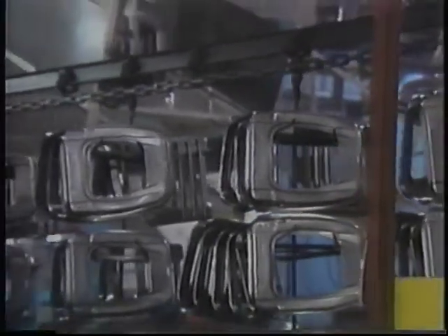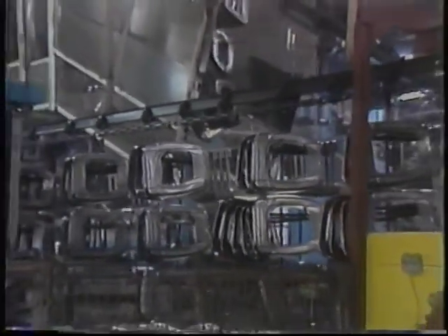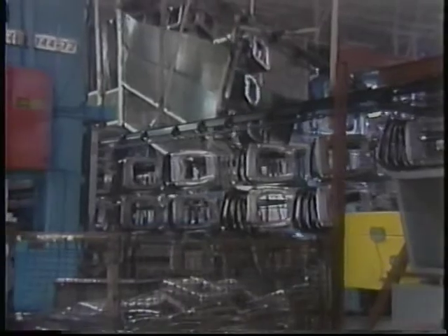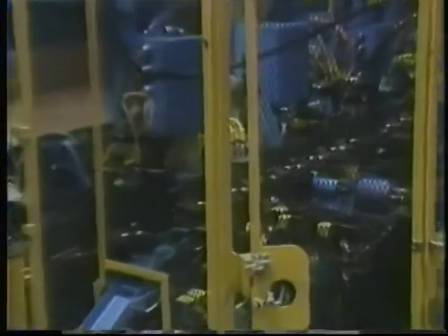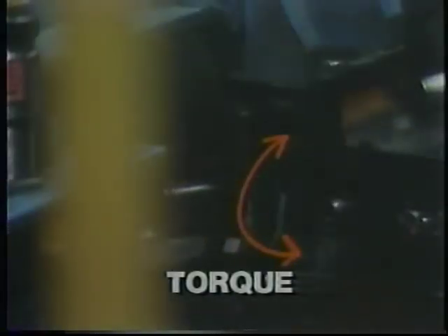The load a motor is driving may rotate like a fan blade or pump impeller used to move air or a fluid, or the load may move in a straight line like a conveyor belt, or the mechanism which moves the cutting head on a milling machine. But however the load moves, a motor's shaft rotates, so the force it exerts is always a twisting or turning force called torque. A straight line force, or ordinary push and pull, can be measured in pounds or newtons, but